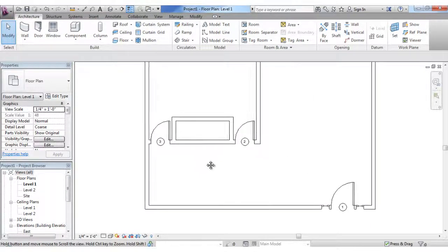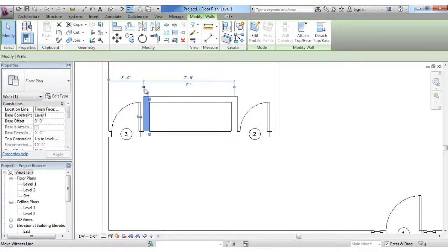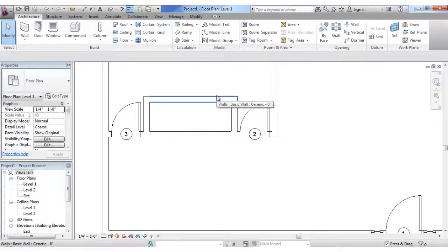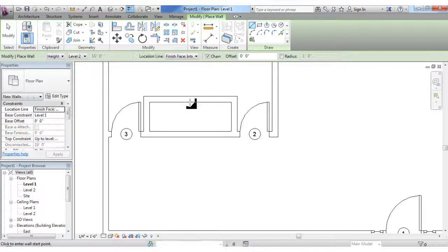You see what's happening here? All right, let's see how big this is. We're going to measure the inside of it to see how big we want our doors to be, because we have to load another door family. We have 7 feet, so we're going to use a double panel door to get into this space. And we may do 2 sides of the closet here. Now that kind of takes away from the space, but it does help the rod be more secure. So let's draw one more wall right here, midpoint.